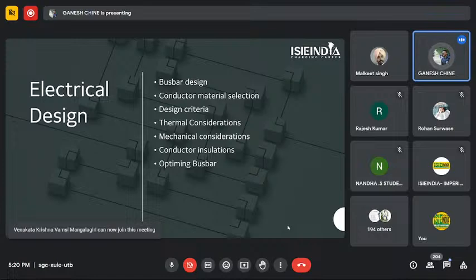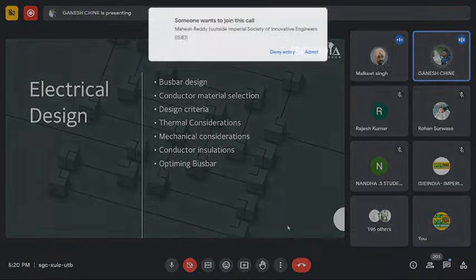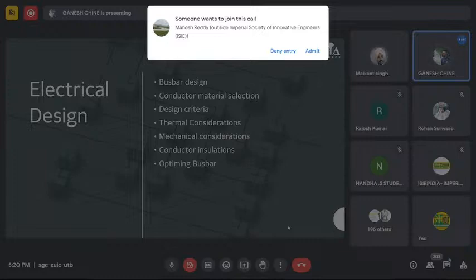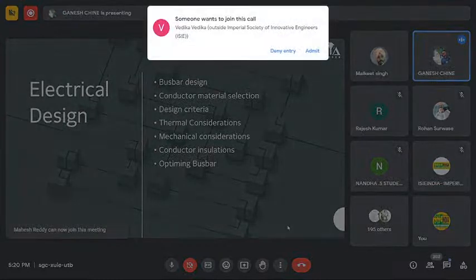When we require high voltage, at that time we use the cells in series, and when we require high capacity, at that time we use the cells in parallel.